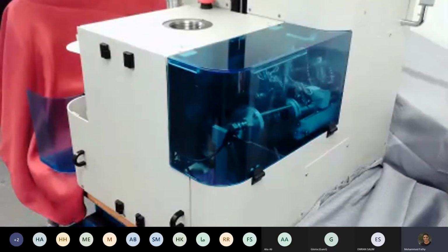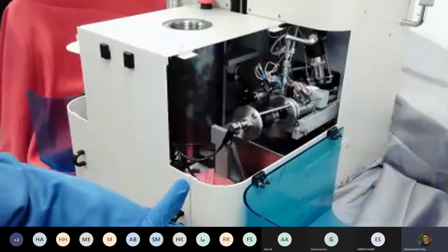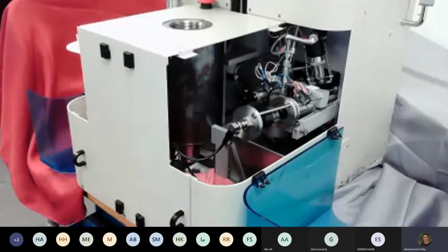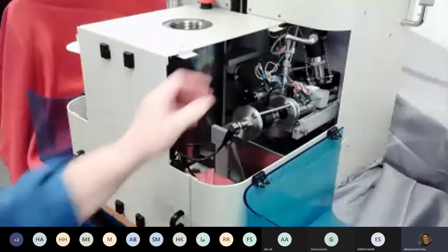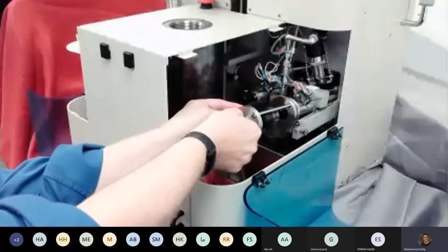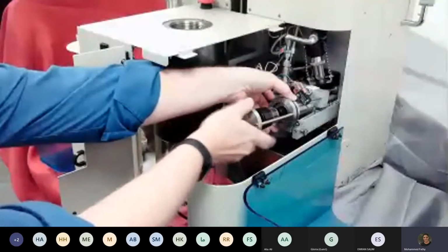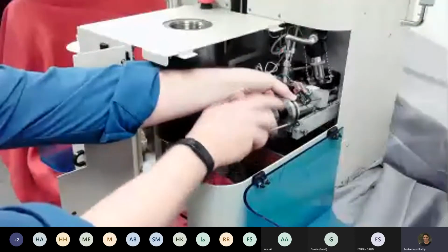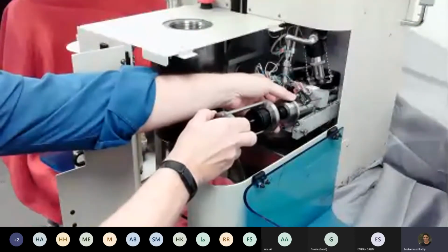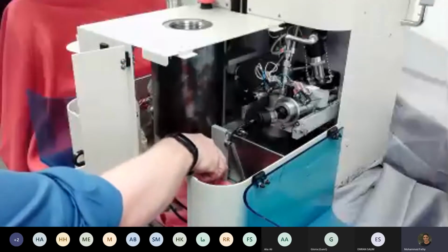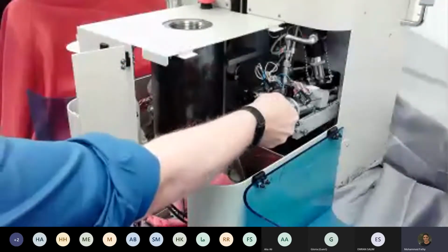Because of that hysteresis, or more specifically, the entrapment of mercury, if in the low pressure system some mercury is intruded, and then when it comes back to atmospheric pressure, some of the mercury comes back out, it extrudes back out, but not all of it, the instrument can refill the penetrometer stem. So we can always have the maximum capacity, measurement capacity for volume in the high pressure